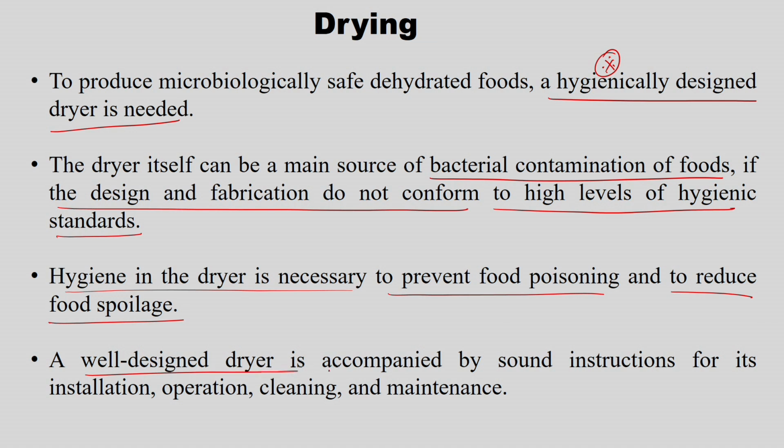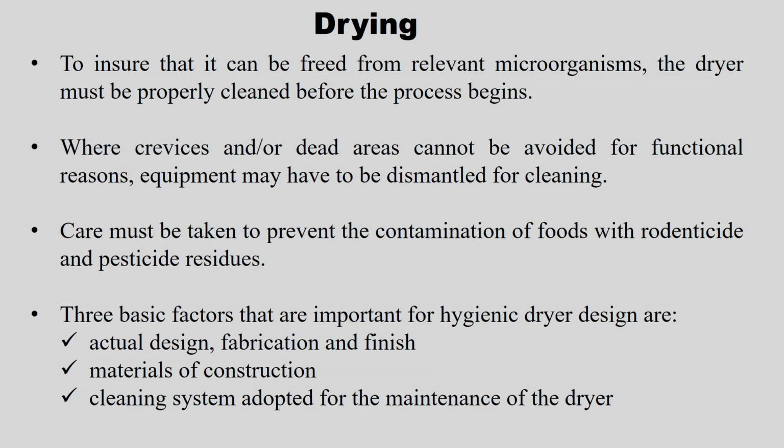A well designed dryer is accompanied by sound instructions for its installation, operation, cleaning and maintenance. So this is to be considered while designing and fabricating the dryer itself. To ensure that it is free from relevant microorganisms, the dryer must be properly cleaned before the process begins. Where crevices and dead areas cannot be avoided for functional reasons, equipment may have to be dismantled for cleaning, right.